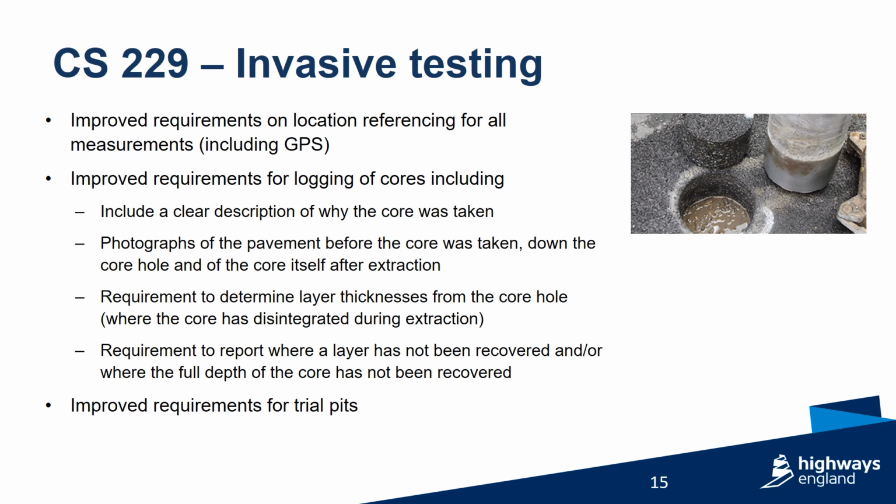A good quality colour photograph is one in focus, evenly lit, and shot with a high resolution camera, so that the aggregate and defects are clearly seen. There are requirements to determine layer thickness where the core has disintegrated during extraction, and report where layers or the full core has disintegrated.